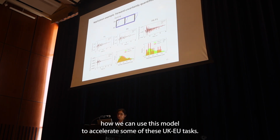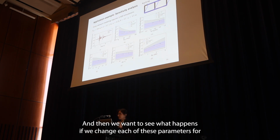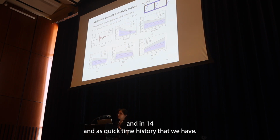So that is one example to show how we can use this model to accelerate some of these UQ tasks. And the other one is if we want to do some sensitivity analysis. In this case, we wanted to consider some nominal values for VS0, K, angle of incidence, and let's say the burial depth. And then we want to see what happens if we change each of these parameters. For that, at first we considered only one excitation, and then we said, what if we run it under all 14 earthquake time histories that we have.